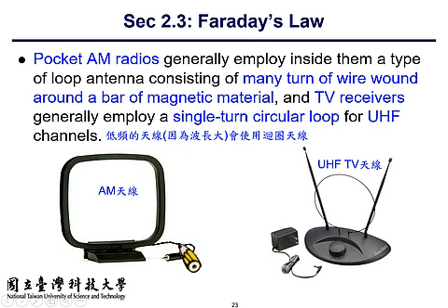And here are a few examples of loop antennas. As I already told you before, for AM radios, the wavelength of the AM frequency is about 300 meters. So instead of using the so-called monopole antenna, which amounts to at least a quarter wavelength of the frequency, you use long wires, forming loops, to do reception of radio signals.